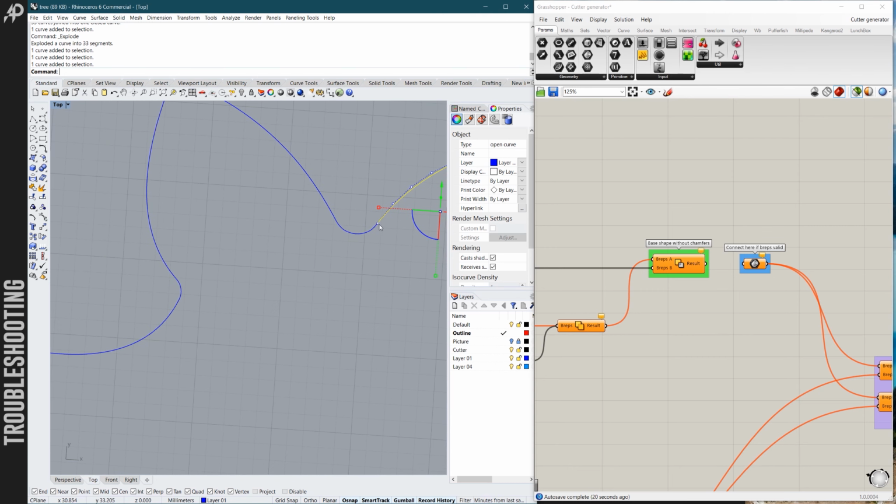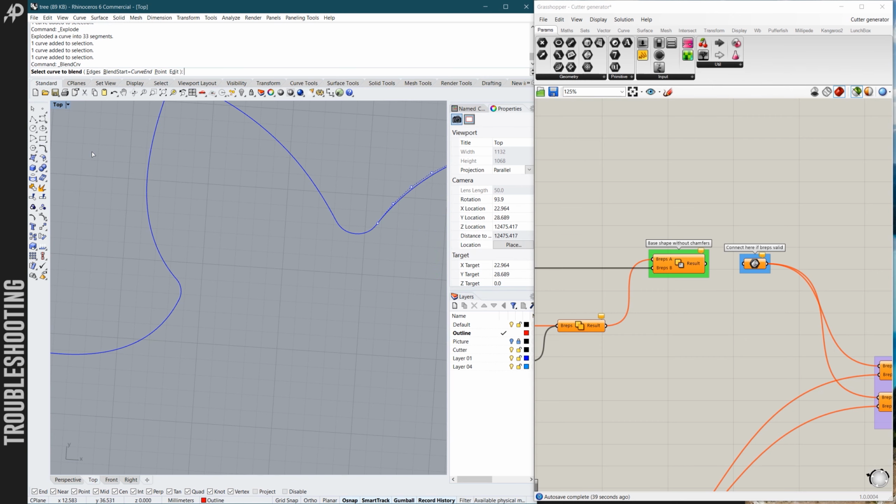I will have to find a respective command, and it is here under the fillet curve command, fillet curve group, and it's called adjustable curve blend. And by the way, if you run command using icon, above the command line you can see what you need to type if you wanted to run it using command line. So it's called blend curve.